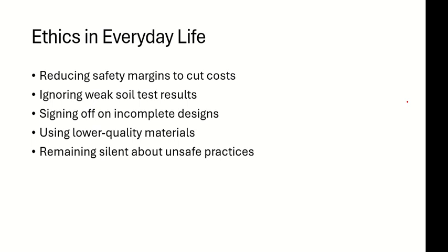You need to change your design to meet the soil report, but you don't change it and you go on with the same design. The client will not know that you have a problem until maybe 6 months, 8 months after the construction, because the soil does not just collapse. It moves very slowly. It absorbs the impact very slowly. So you may not see the impact immediately.